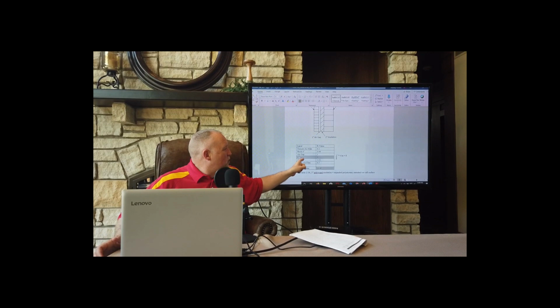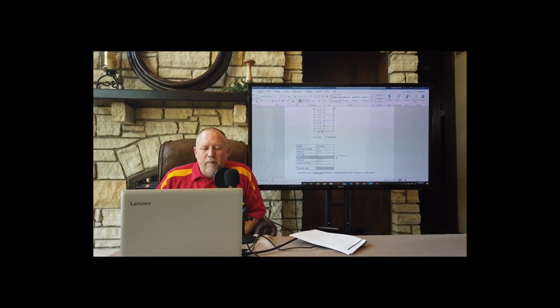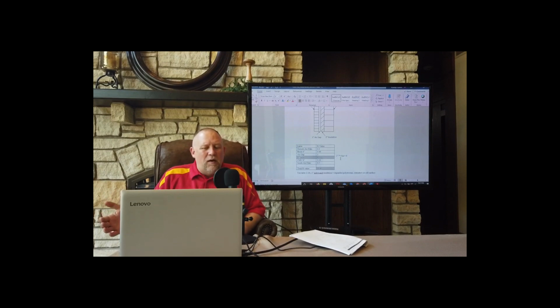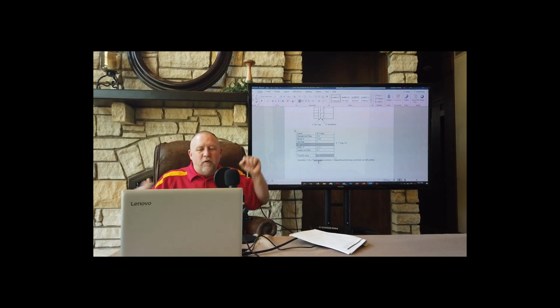It's just that 2 inches of polystyrene, at an R value of 4 per inch, gives you an R value of 8, and now our total is 11.45. You could say that in this wall, maybe the R value of the air is getting kind of negligible, but it's still worth including.